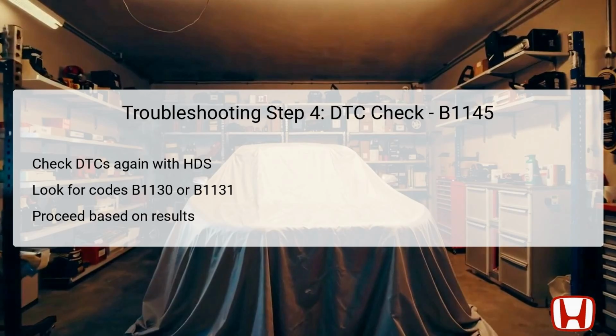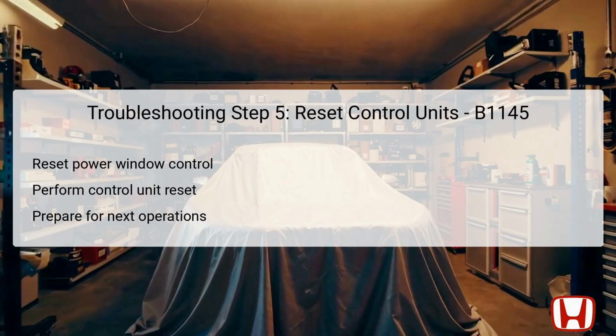Thorough checks at this stage are pivotal, as they help clarify the nature of the fault within the window system. The next troubleshooting step involves resetting both the power window control unit and the front passenger's power window control unit. This reset is crucial for clearing any glitches that may have caused temporary failures in the system.